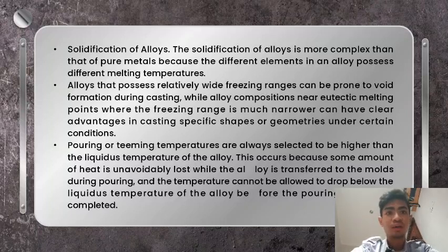For any given alloy composition, the difference between the liquidus and solidus defines the freezing range of the alloy. However, some alloys have a unique alloying composition that eliminates the mushy zone completely. These alloys are referred to as eutectic alloys. Eutectic alloys have a specific melting point that is lower than the individual melting points of either of the constituent elements that comprise the alloy, and this can have important practical consequences during casting.